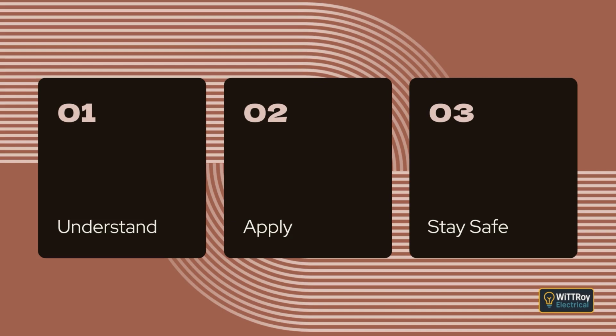Clause 3.14 Safety services. This clause explains that any wiring used for a safety service must meet all the normal installation requirements in this section and must also follow the extra rules set out in section 7.2. Safety services must continue operating during faults or emergencies, so their wiring has stricter reliability and protection requirements than general wiring.